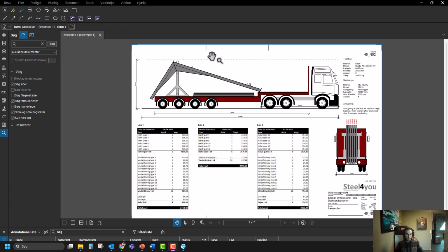So when you have made these thoughts about your transportation, then you can start making your drawings of your elements. Again, when you do some kind of facade view of your walls, then you have to divide them into two, because otherwise they would really be too tall to transport.